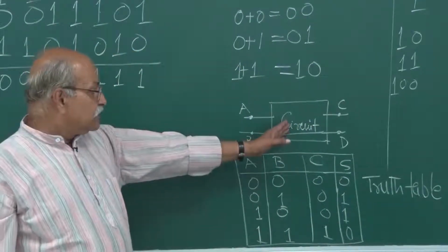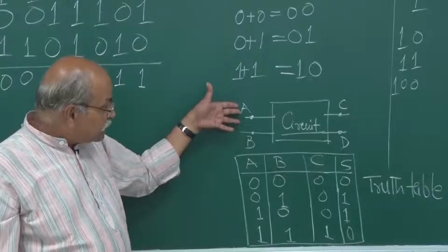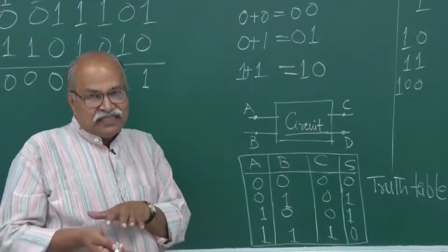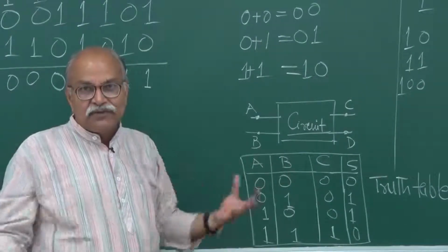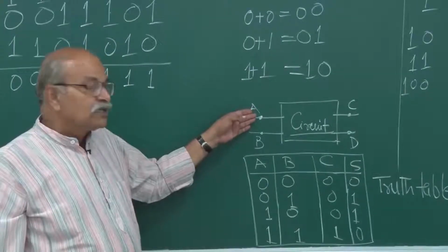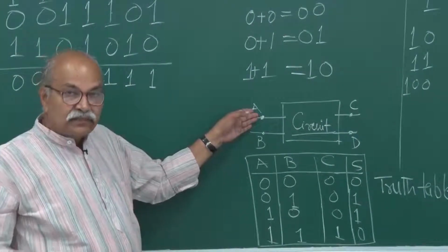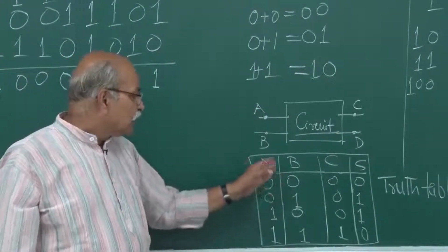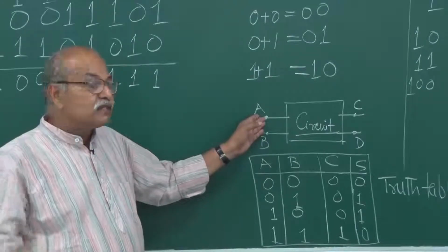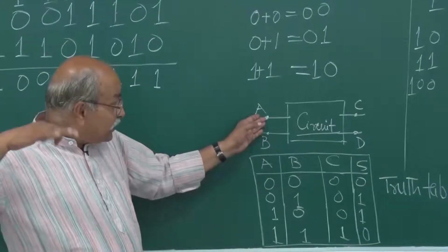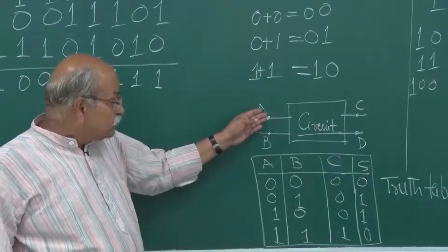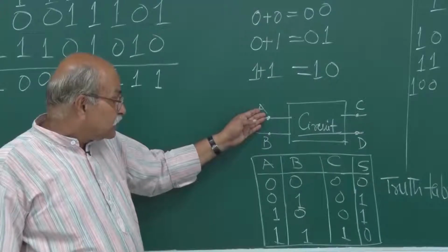And our circuit will take these inputs, that means voltages we will provide, low and high. We have to predefine, normally say 0 to 0.8 volt or 0 to 1 volt is low. So if I apply 0 volt here, 0.5 volt here, that is low, and that will be treated as 0. And anything which is predefined, more than 2 volts, that I can define how much is that, if it is that high voltage, more than 2 volt, then that is 1, and similarly for B.